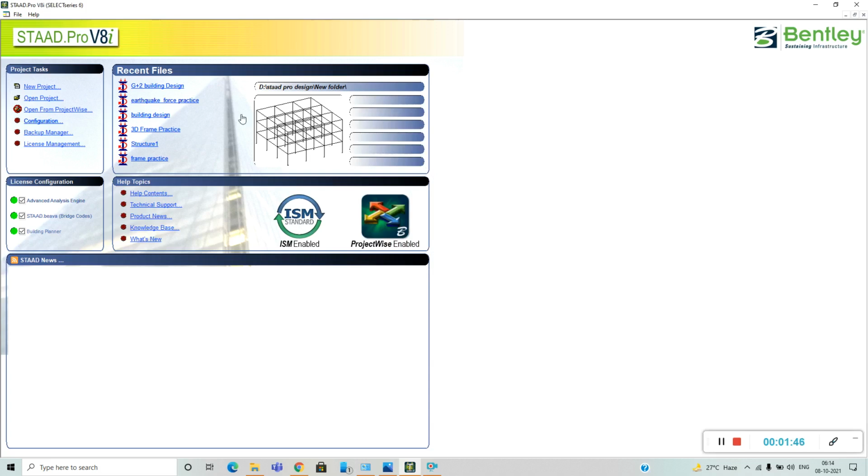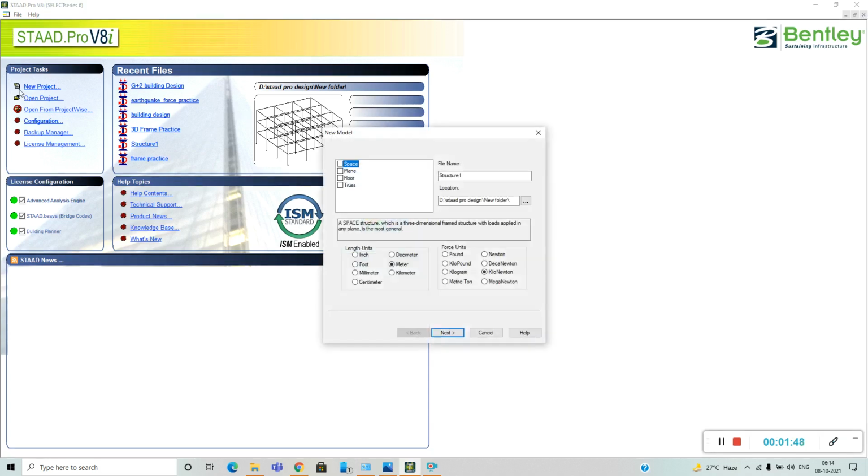Okay, go to new project, click on new project. We want to work in 3 dimensions, X, Y, and Z coordinate. That's why we select the space and length unit meter, force unit kilonewton, and first of all we give the project name. We give the project name as design and analysis of building,